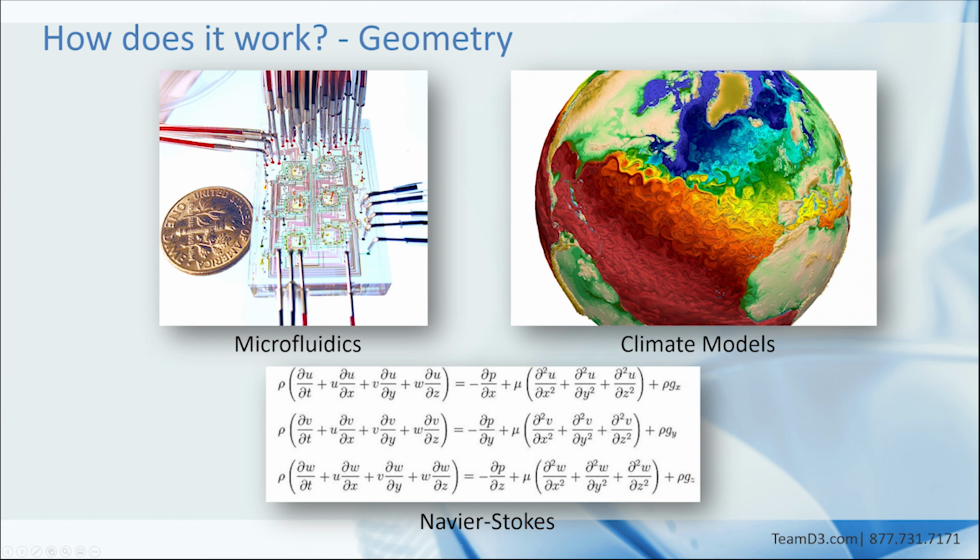A climate model of the entire planet? While you could think of it as a CFD problem, it's not the type of problem we will be solving with a general-purpose engineering software application. The bottom line, if you're unsure whether your application is appropriate for your solver, look at the governing equations your solver uses and determine if those are appropriate for the physics you're trying to simulate. For most manufacturers, Navier-Stokes is going to fit.